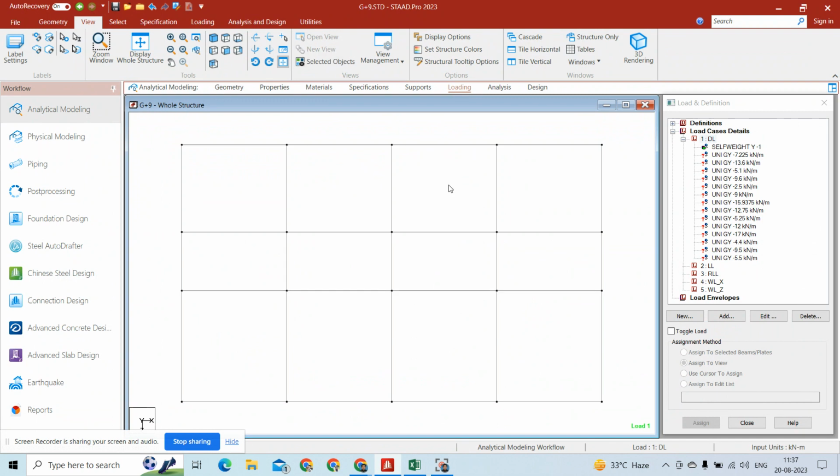I will assign into all the interior beams, but not all, because here it is the stair block and there should be some opening. This is corridor, this should also have opening. There is lift box, here also should have opening. As it is a lift box, it will be provided with the shear wall, so no brick wall load will be inputted here.